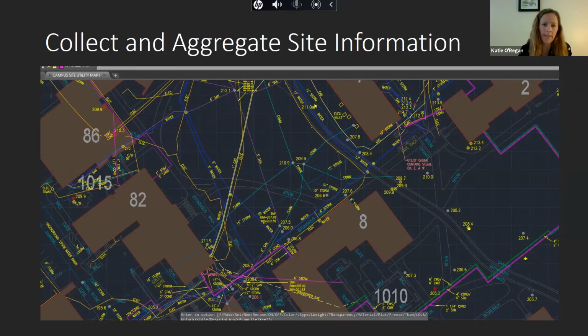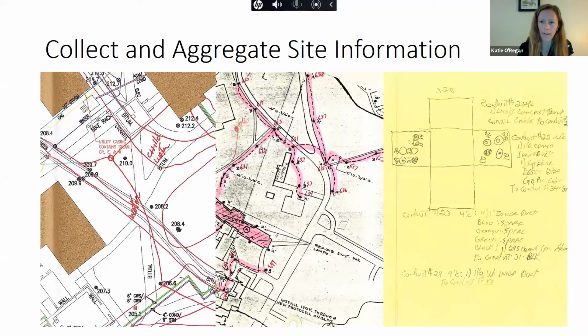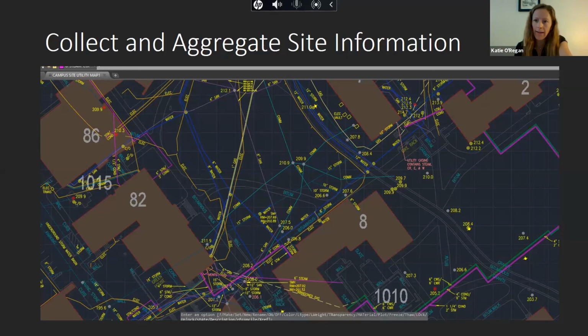So Leo, in the process of importing a plan like that, where they already had some layers defined, I'm assuming the colors are by layer, like the blue is water line, green might be gas, or yellow is gas. So when you brought that into the GIS, it preserved some of those layers, so you were able to then reassign those lines to the specific database fields that were in the GIS.